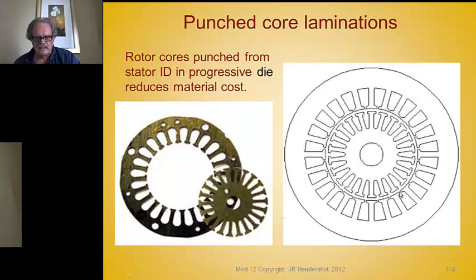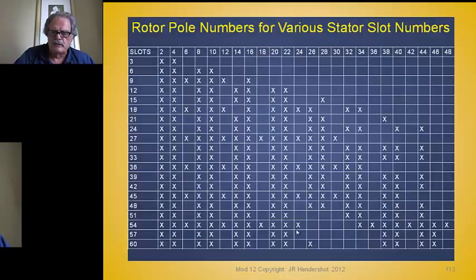And the sides of the teeth should have tapers on them. There can be a radius right there. That's okay for a radius there. But the sides of the teeth should have taper. The length of the tooth tip that extends past the side of the tooth, in other words the distance from here to here, should equal that distance there to avoid saturation. So the tooth tip protrusion should be equal to the throat thickness, or the attachment of the tooth tip to the tooth.